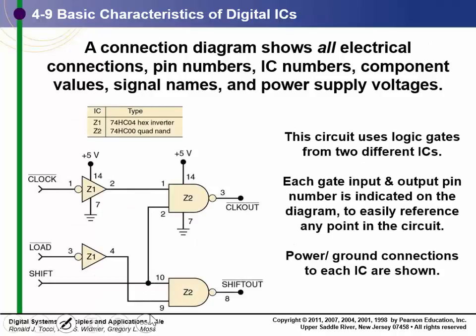Okay, this gets a little bit into the circuit board design part of things. If you're going to lay out a circuit with a CAD package, and we won't be doing that in this class, unfortunately, but if you're going to use a package like OrCAD or Multisim or Ultiboard to design the circuit, typically you would assign a part number to every IC on the board.